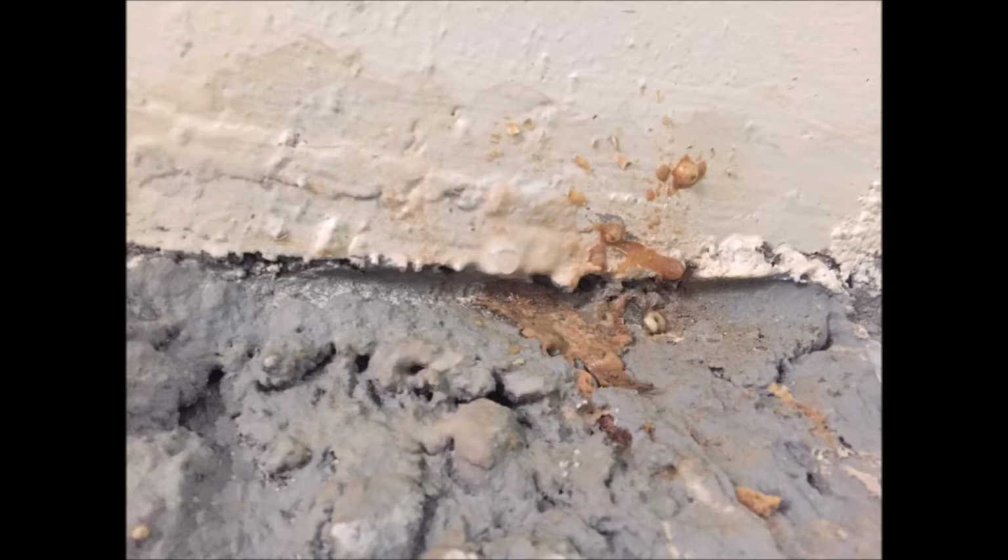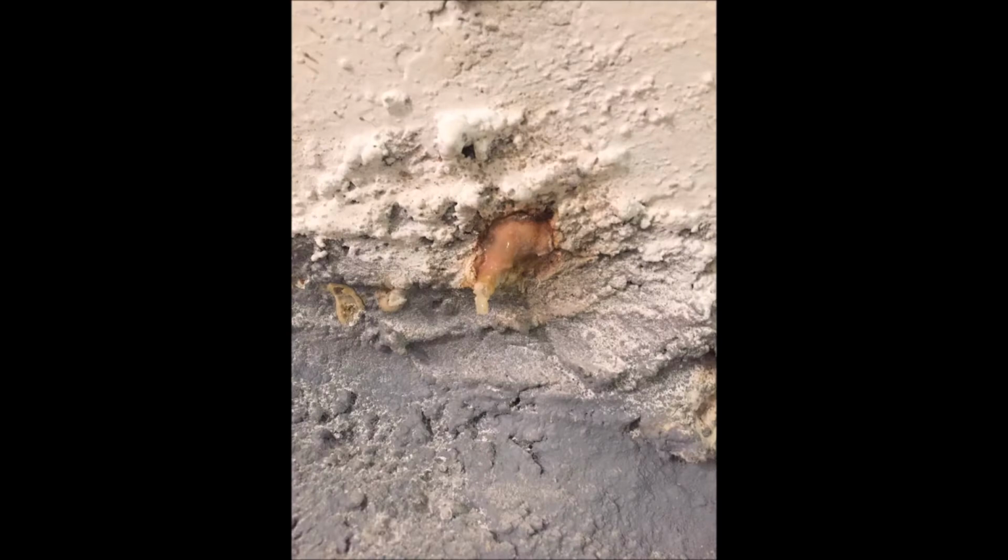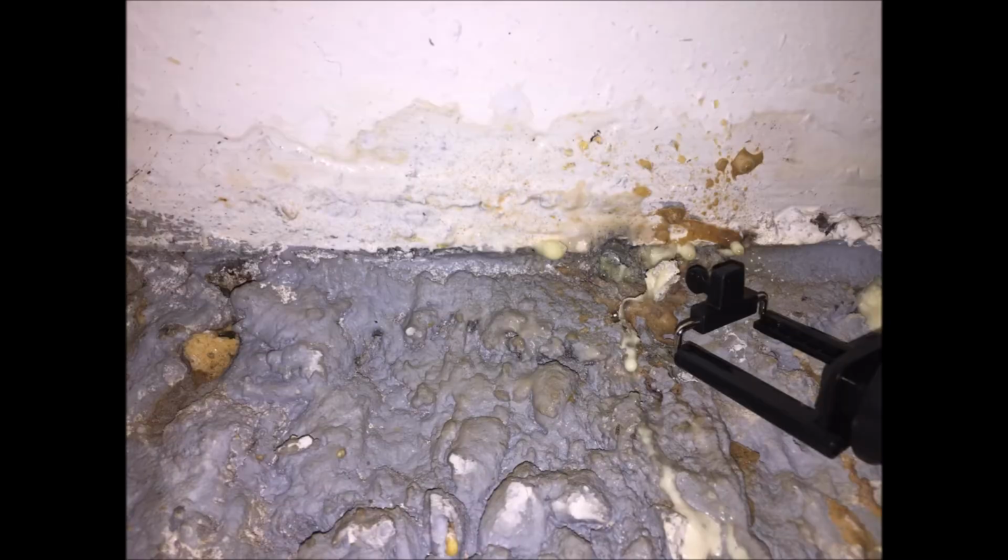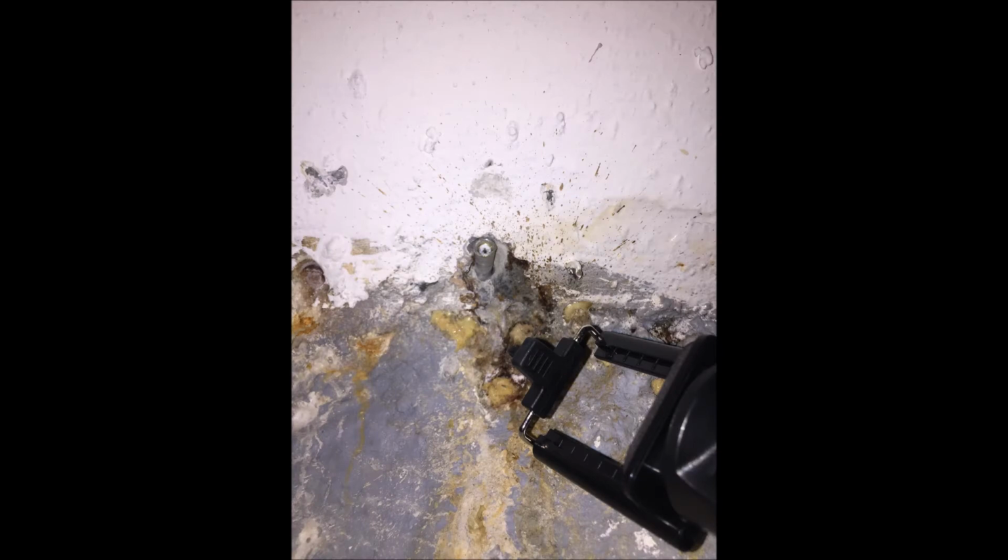So yes, here are the implications. How to prevent efflorescence in a building. We use cement gauge lime mortars or moderately hydraulic lime mortar or cement mortar, with small proportions of alum and soft soap throughout the work if possible, then the use of waterproof mortar. Secondly, the use of damp-proof courses should be made wherever necessary. Third, only burnt bricks and clean water free from salt should be used. Fourthly, the masonry or plaster work should be well protected at night during rain to exclude extra water.